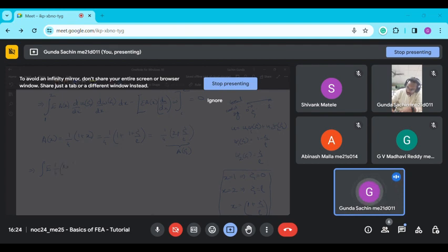So your weak form for element 2 will be here: E, A of zeta is 1 by 4 times 2 plus zeta by L, and du by dx is u1 times minus 1 by L plus u2 times 1 by L. For w is equal to psi 1, which is minus 1 by L, and the right side we will just write as maybe q1.